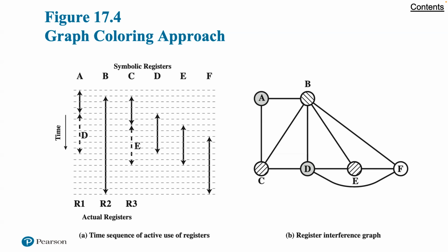Their studies showed that with even simple register optimization, there is little benefit to the use of more than 64 registers. With reasonably sophisticated register optimization techniques, there are only marginal performance improvements with more than 32 registers. Finally, they noted that with a small number of registers, for example 16, a machine with a shared register organization executes faster than one with a split organization.